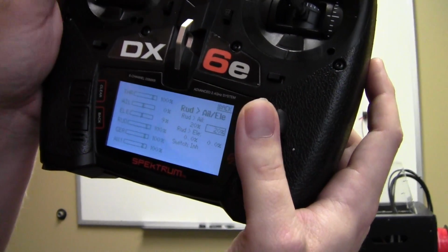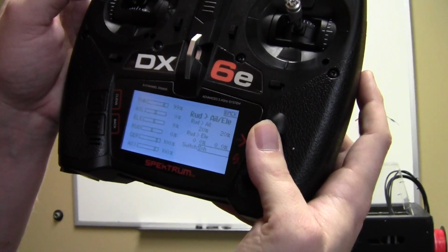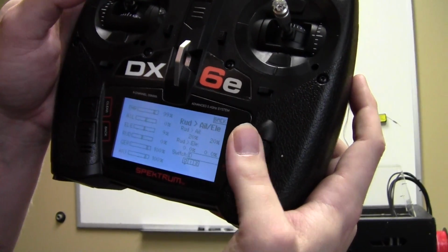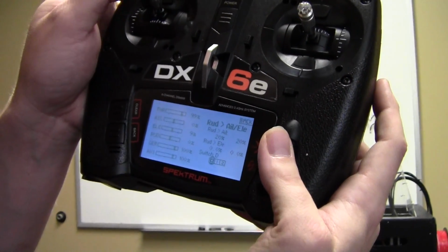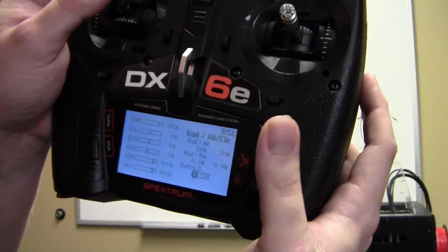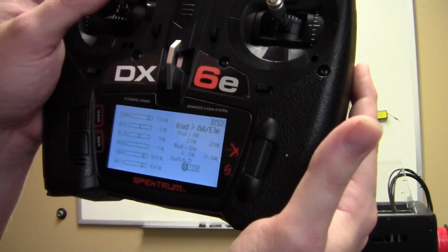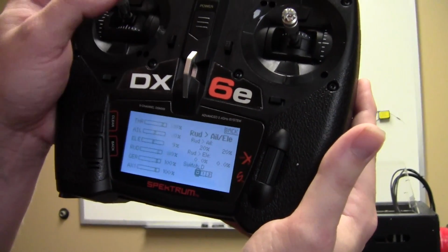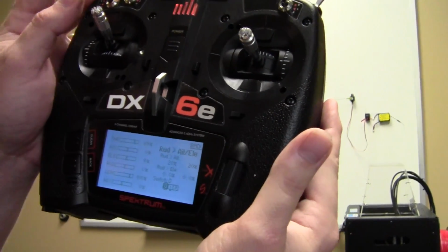And if you look at the monitor, then we want to put it on a switch, put it on the D switch. So when we look at the monitor, when our switch is up, we'll call it our stall turn mode. You see the aileron deflects with the rudder. But let's say we don't want that all the time. We want it to be normal without that.